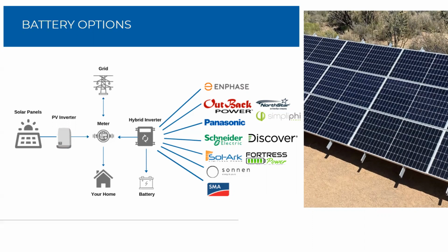And then we have another one from earlier that says, when sizing AC coupled systems to power a critical loads panel, is the sizing requirement to be able to power the largest branch circuit? So that's a really, really good question, actually. You could size it based on the worst case scenario, which would basically be the entire loads panel running simultaneously. However, a lot of this comes down to homeowner education.